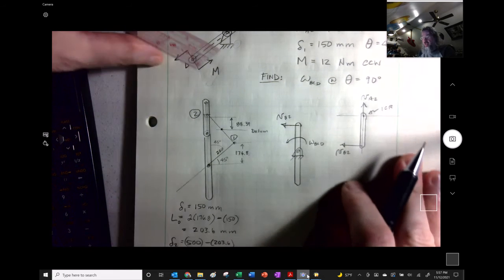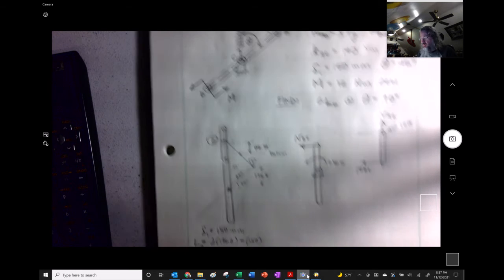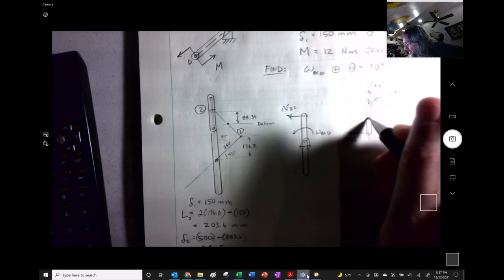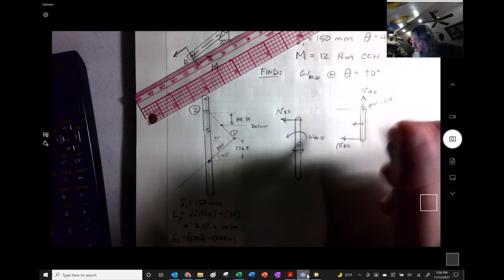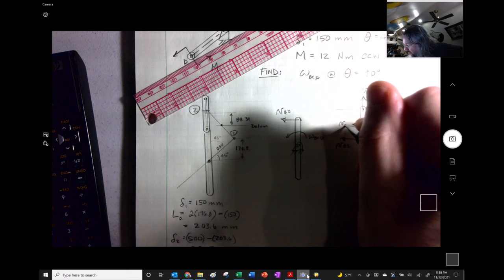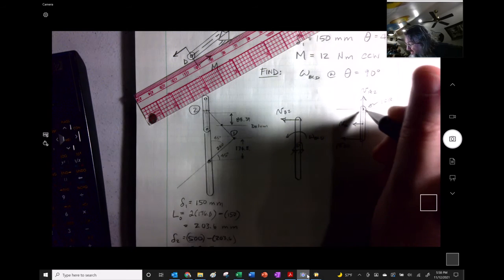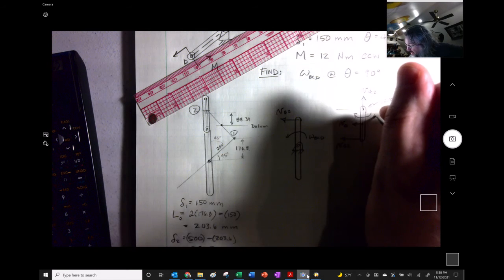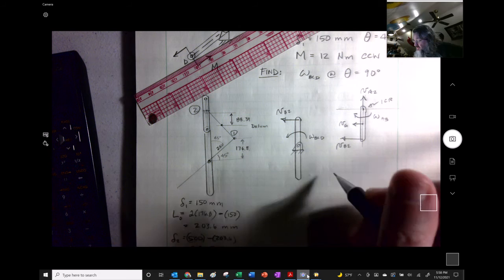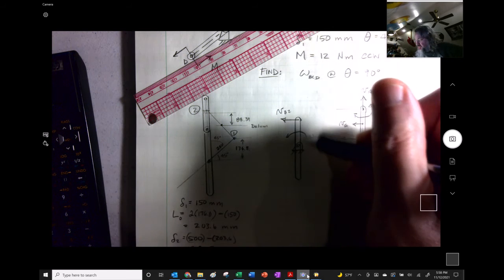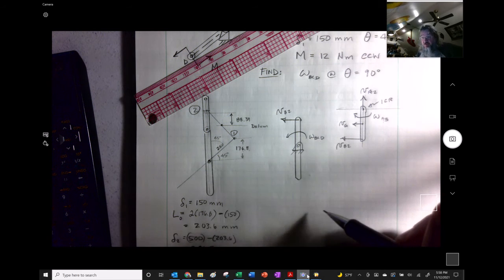But that kind of makes sense if you look at the mechanism, as it's going to reach its peak here, and then it's going to start coming back down once this thing has gone through. So that's okay as the ICR. But what makes this a little bit messed up is that now that right there is going to be the velocity of the center of gravity of the piece right there. I'll just call it VG. I don't need to use any other VGs. And also we know this thing has an angular velocity right there of AB. And it's fortunate for us these are the same lengths. So this is actually going to be this. They're going to be equal to each other, even though they're opposite in direction.